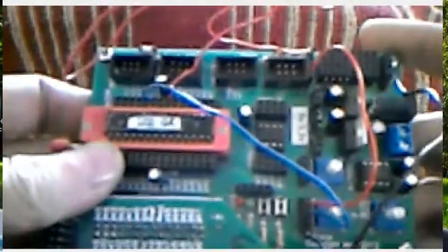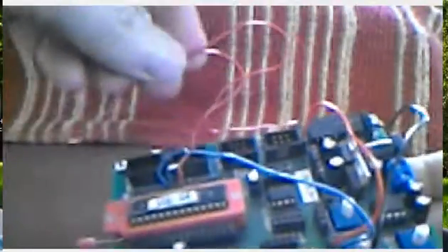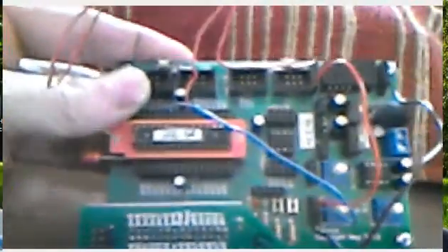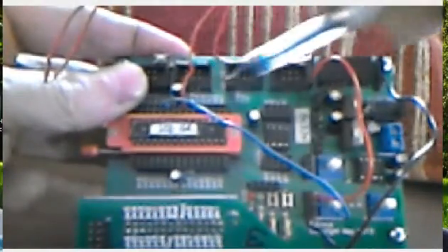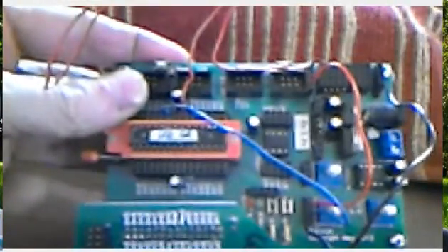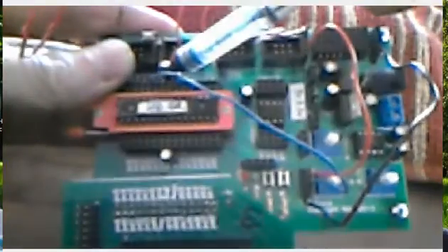And then the last bit that I need to do to make it work is connect my V reference. Here I've got a long wire, that's the best I could do, I don't have any short ones, but this wire connects the V reference, which is right here, to 5 volts, which is right over there. Then I also needed to connect my PC0 right here, and it goes to, in this case, a potentiometer, this one.